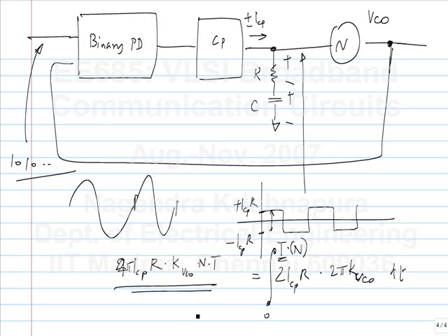Okay. So, that is the jitter. I mean, this will be there even in the ideal case. If the data has no jitter, the VCO has no noise, no other components have noise, simply because of the digital action of the control loop, you will have this jitter. Okay.